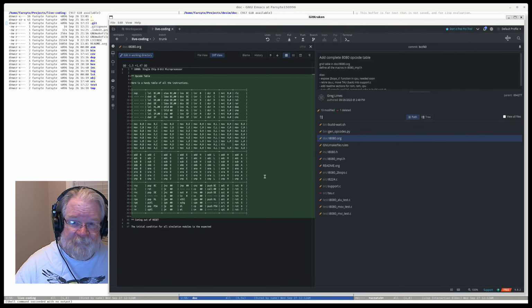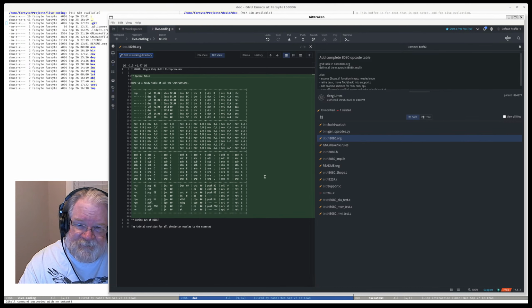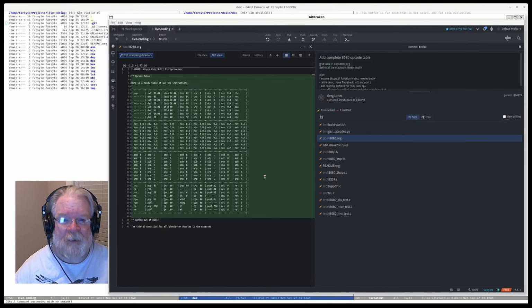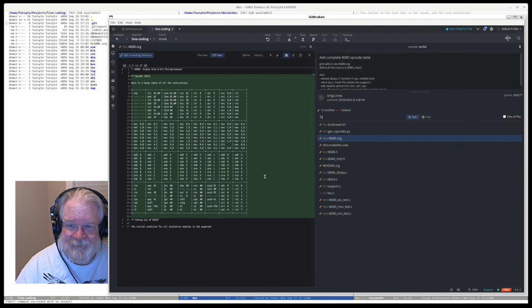Different chips from different manufacturers may do different things with those opcodes. And because of the way these things work, the same chip in two different systems may do different things. For instance, if it is reading from the data bus into a register, and it's latching the value into the register, but it's not also turning on any drivers to the data bus, then what you will get will depend on what that data bus floats to in that system, okay? So these dashed lines, you can't even say that they're going to have consistent behavior from system to system.